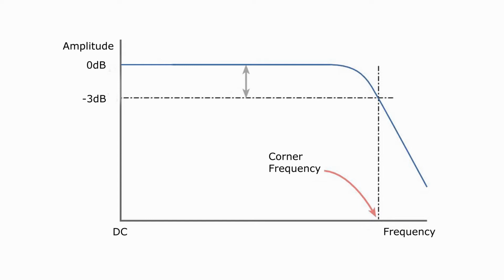There are two limitations to analog to digital converters. The first is the sampling rate, and the second is the smallest resolvable voltage. Both of these limitations play a factor in defining the optimal setting of the low-pass filter's corner frequency.